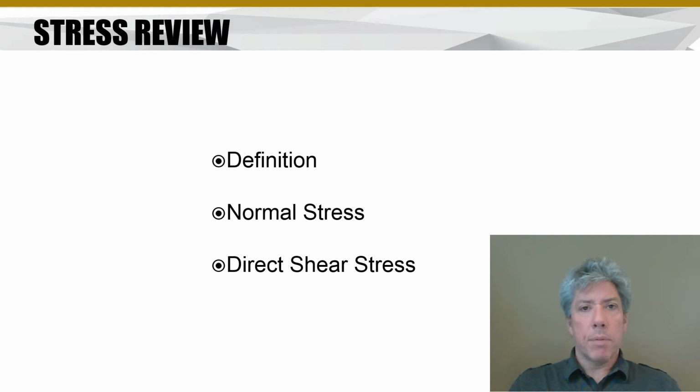Now, unlike pressure, well, actually pressure can have negative values too in liquids. But stress can have positive or negative values. Basically, positive values are tension and negative values are compression. That's a little bit different than regular pressure because regular pressure is usually compressive, of course, and so that's what we're calling a negative stress instead of positive, whereas pressure would be positive in that case.